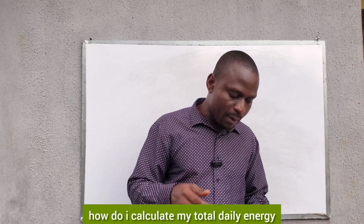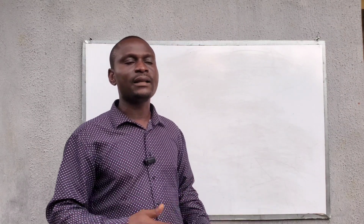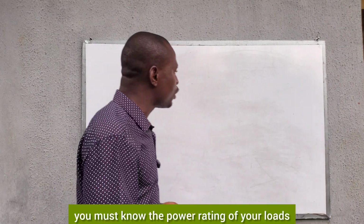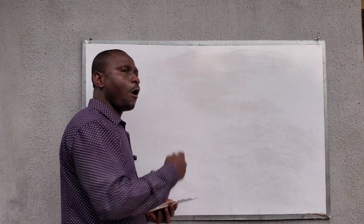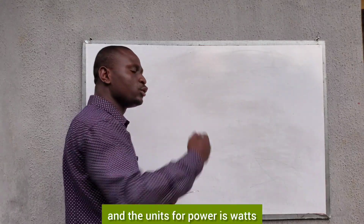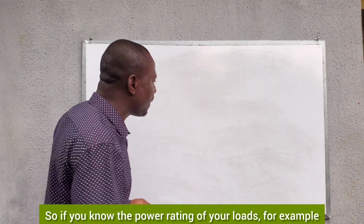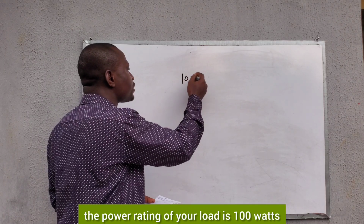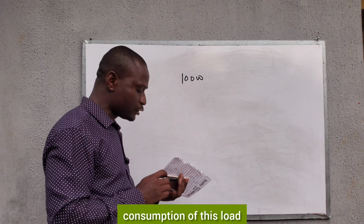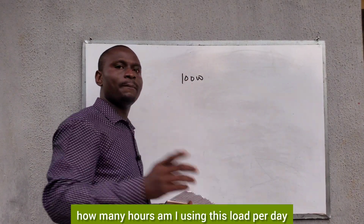Then we have question number 9. How do I calculate my total daily energy consumption? I mentioned this earlier, that for you to calculate your total daily energy consumption, you must know the power rating of your loads. All electrical appliances are rated in watts. We call it power, and the unit for power is watts. So if you know the power rating of your load, for example, 100 watts, and you want to know the total daily energy consumption of this load, you will ask yourself, how many hours am I using this load per day?